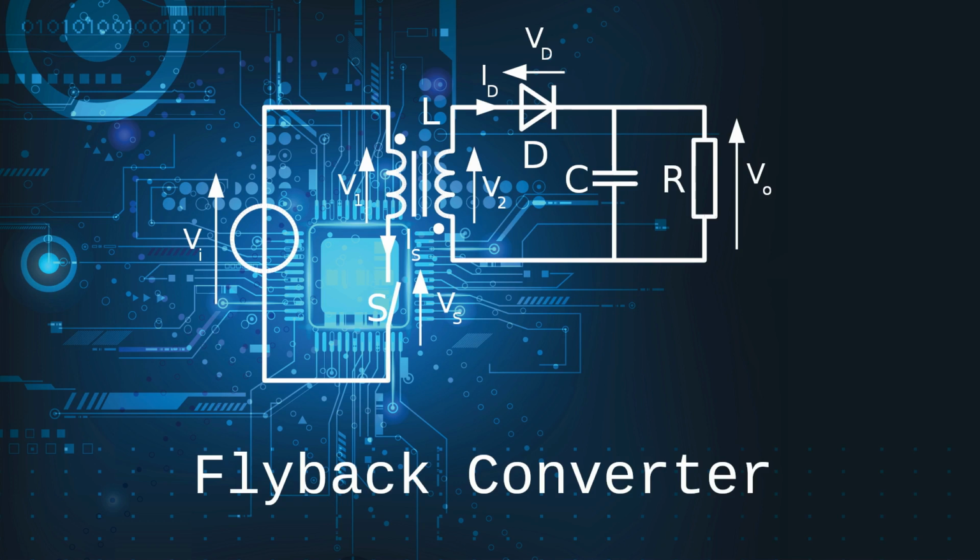Input is a DC that is converted again to another DC at the output. Mostly this will be used for step down. Input DC generally will be AC 230 volts rectified into around 270 volt DC. So the DC will be converted into 5 volt DC so that batteries in mobile phones can be charged.